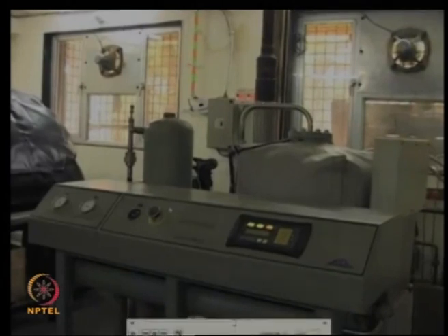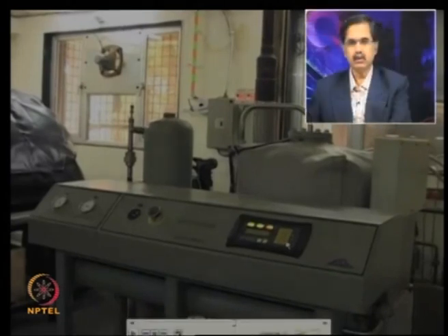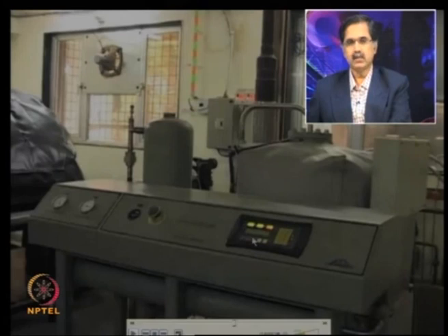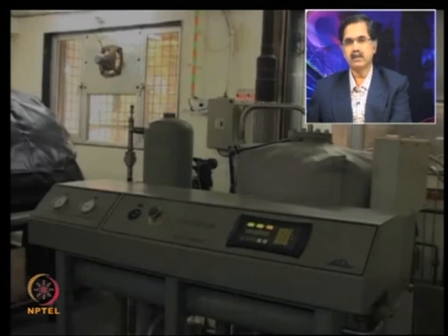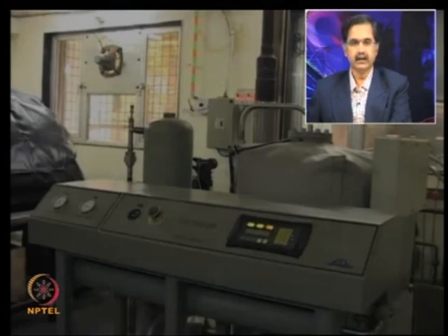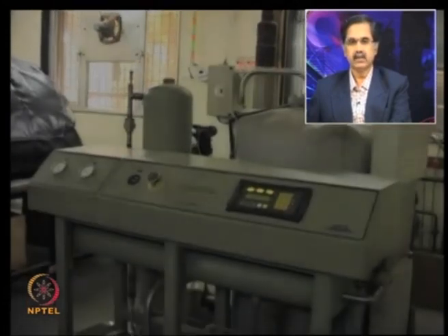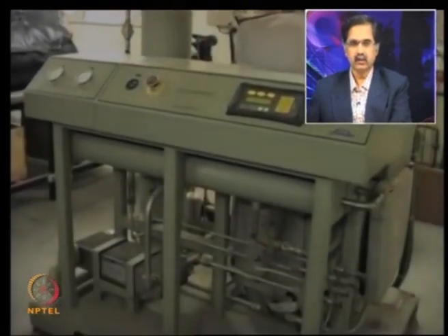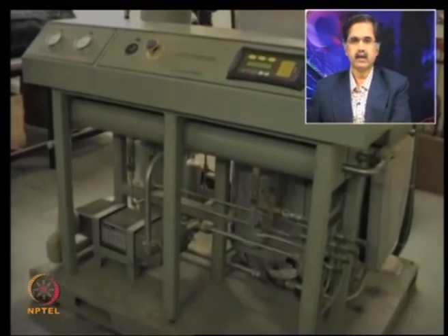So, now let us come to the compressor. That was what the cold box was all about, and this is now the compressor, which is the most important thing. This compressor is a screw type compressor, and it compresses the gas from around 1.2 bar to around 17 or 18 bar, all right, with a flow rate of 12 to 18 grams per second of helium. So, you can see this compressor. This compressor is going to be water cooled because the temperature after compression is going to be very high.